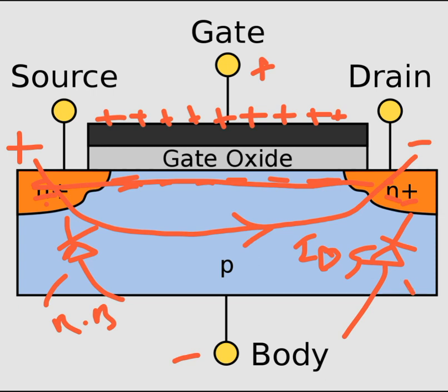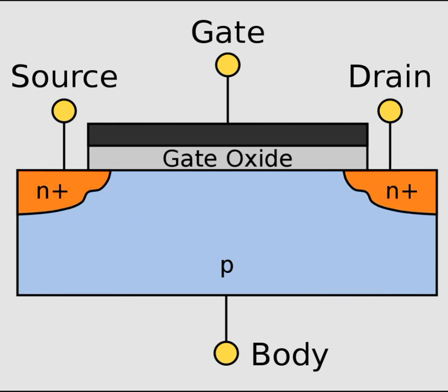So this diode is also not getting forward bias. So clearly that's a situation which is favorable, because if one of these diodes or both get forward bias, there will be a current through the junctions which will interfere with the operation of the transistor, which is FET.